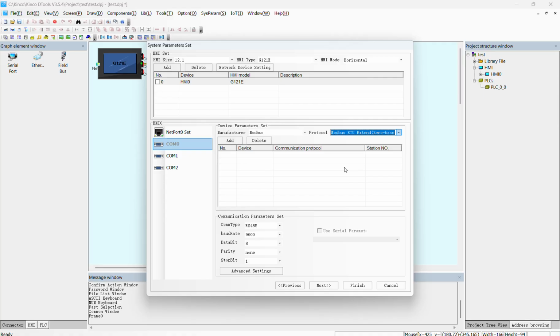For example, if your VFD operation address is 200, you just need to enter the same here. You don't need to calculate anything for your address. Just make a communication, and here you also need to add the station address, which you can change, for example, like this.